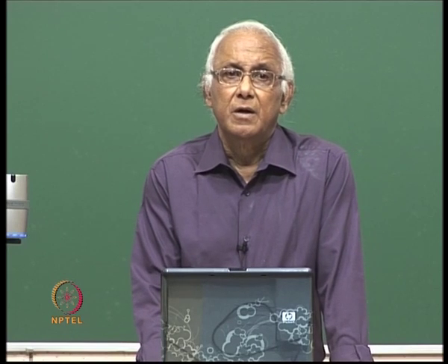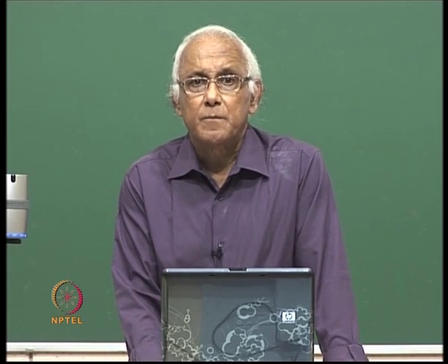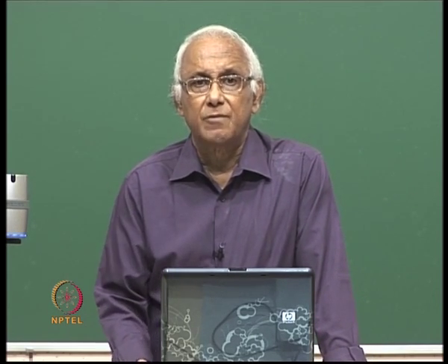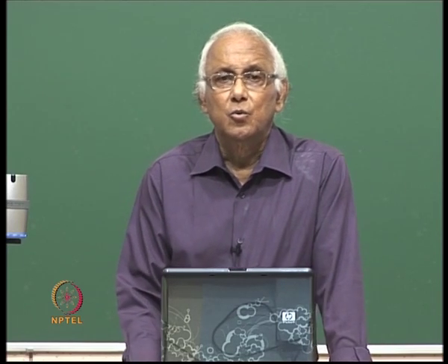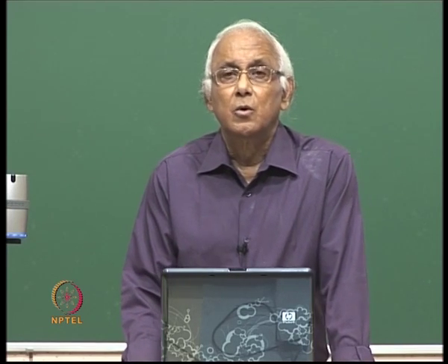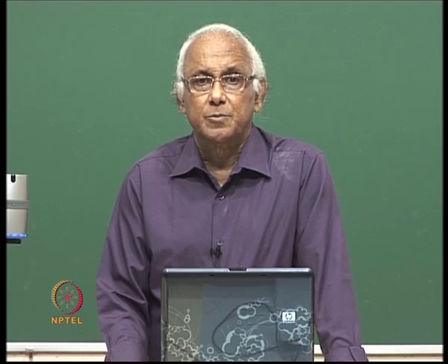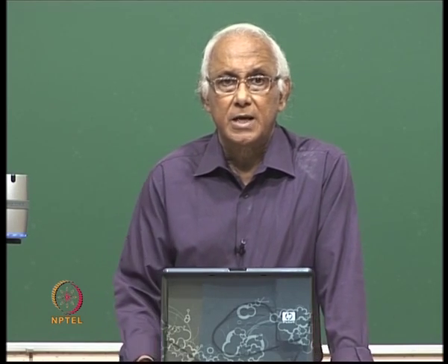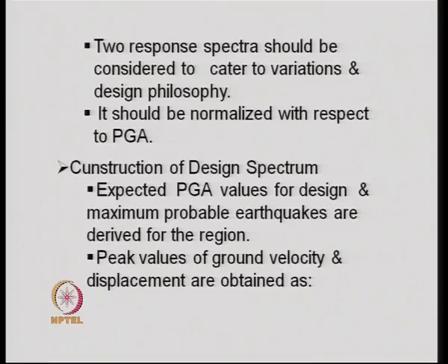It can have a huge amount of damage. So, this is the current design philosophy, and therefore, we have to have two level response spectrum. One is the design response spectrum, the other is the extreme response spectrum.